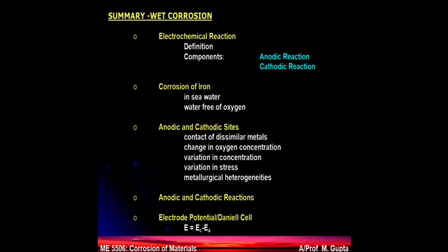So very quickly, in wet corrosion we have learned that its principles are totally different from dry corrosion. The relative humidity value which demarcates dry corrosion from wet corrosion is about 60 to 65% range. In Singapore conditions, for example, because all of you are in Singapore, you must understand that average humidity levels are between 80 to 85%. So if you put anything outside, outdoor, you are exposing the material to not dry corrosion but the wet corrosion category. So two categories: dry corrosion works in a different way, wet corrosion works in a different way.